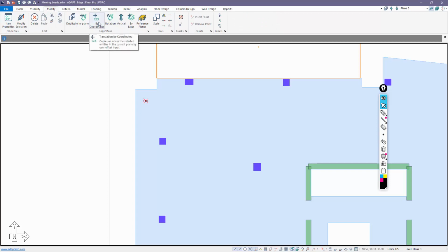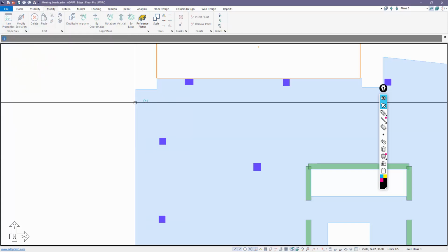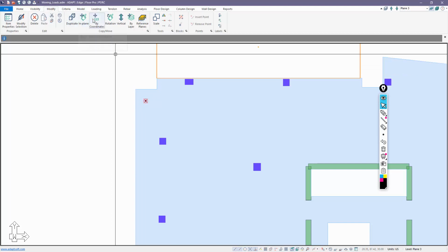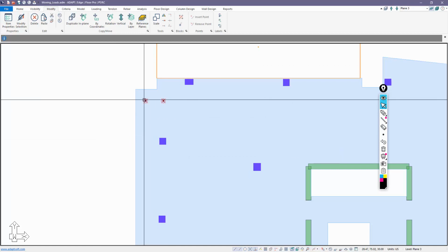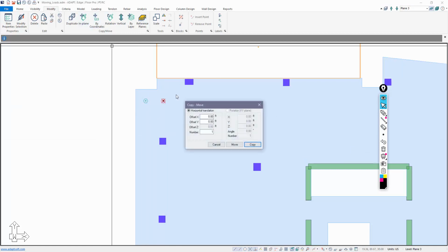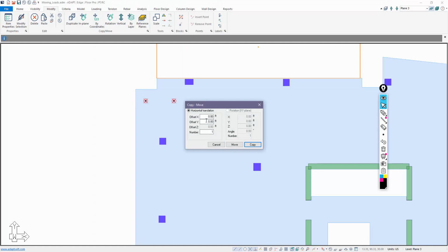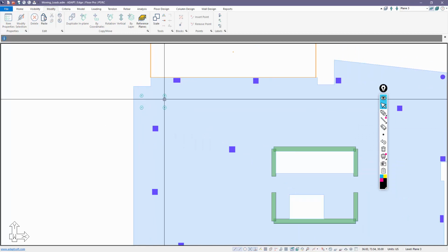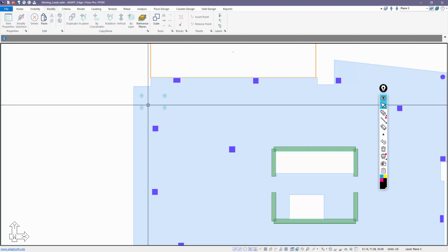I'm going to modify this. Let's go ahead and set that to 5 kips. This is in the Z direction downward, and I'll take that and just modify it by coordinates, and I'll copy that over 5 feet. Or excuse me, that should have been copied 8 feet. Let me move it an additional 3 feet. And then I'll copy these down 4 feet. So this will be in the negative Y direction, -4, copy. There's my load pattern for this set of point loads and 2 axles, let's say.